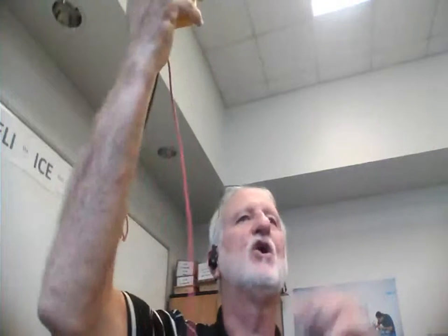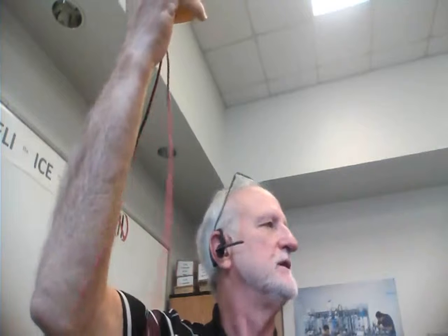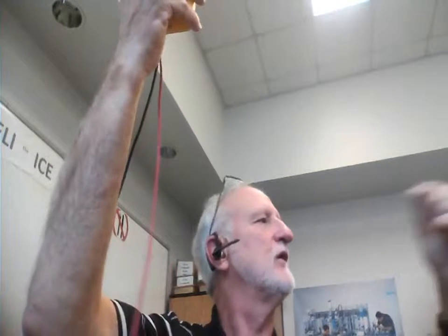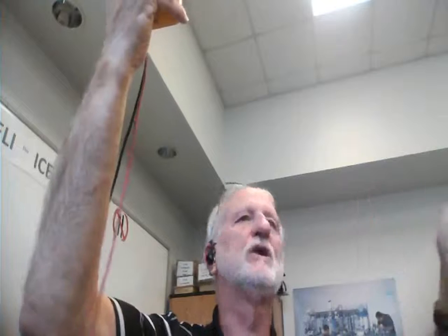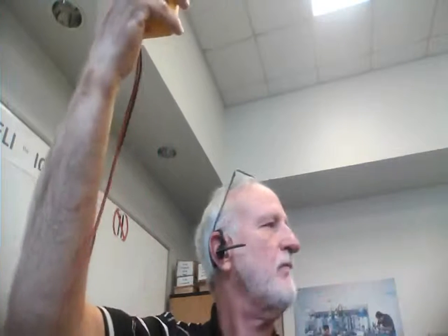But if you actually want to see it work, then you're going to have to use a device called an oscilloscope, which actually shows you what's there. So a meter's nice, but a meter averages everything, right? A meter is not showing you what's there. It's giving you an average of what's there. So if it's got a pulse stream coming out, all these incremental encoders, it's not going to show you the pulses. It's not going to show you the duration of the pulses. What's it going to do? It's going to give you a DC average.